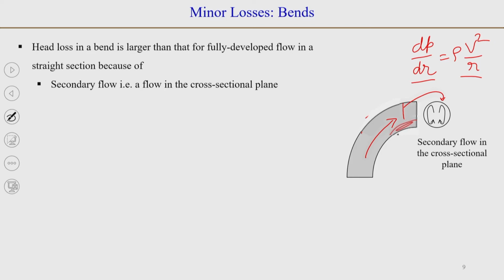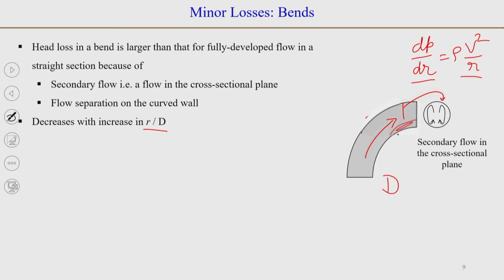And the strength of these vortices depends on a non-dimensional number, which is called the Dean number, and this is basically equal to Reynolds number into square root of R by R c, or if we use the nomenclature here, R c is basically small r, where small r is the radius of curvature and capital R is the radius of this pipe here.